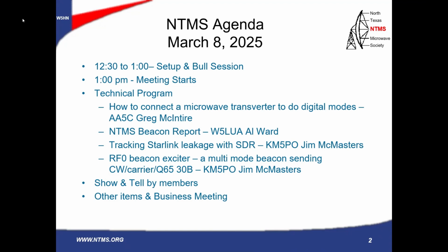Mini Circuits is now selling a 3-watt amplifier for 10 gigahertz and a secondary part, which is 3 watts from 10 megahertz to 10 gigahertz and everything in between. One of the chaps in Belgium has done a board for it. I had 50 of the boards made up, purchased 60 of the chips and took those to the UK so guys can build 3-watt amplifiers. The chip cannot be installed by a human. It has to be machine installed.